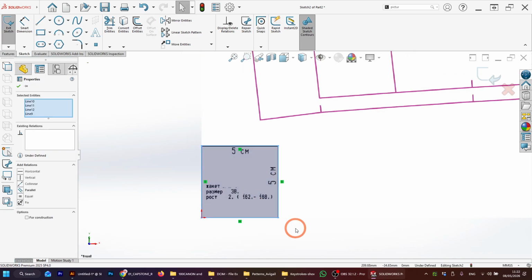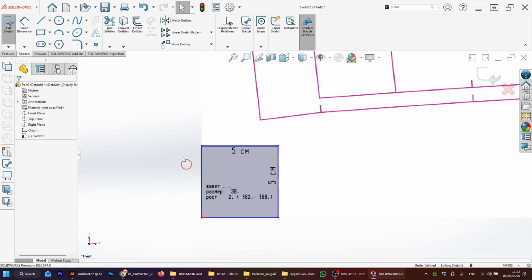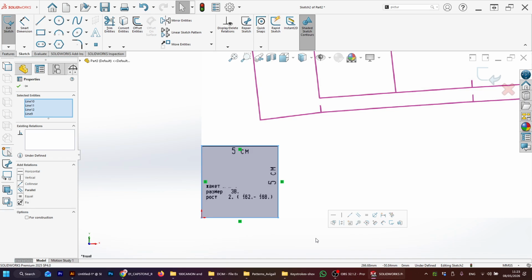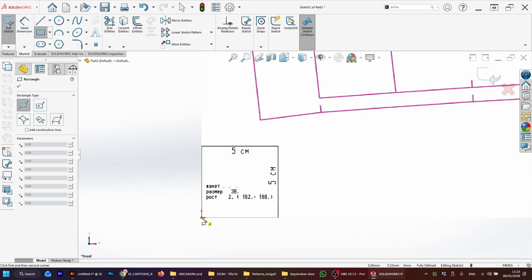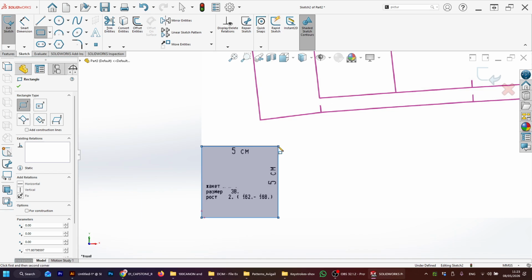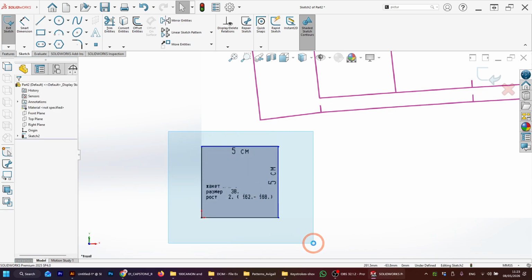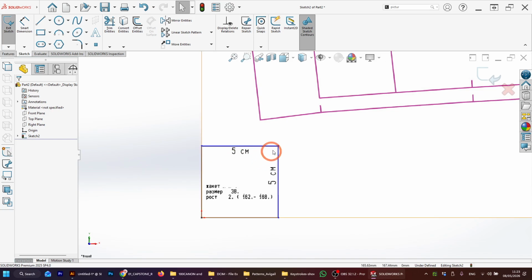Okay, actually I want to do it correctly. I made a mistake. I can always select everything and delete on the keyboard, but the button that's written del, D-E-L, not the backspace, not the back arrow. I want del. So if I click on this delete, then it deletes. So I want the corner rectangle. I start from the 0, XY0 point that never moves, and I sketch it as clean as I can. Select everything, equal. Now I know it's a perfect square. It's my dimension.